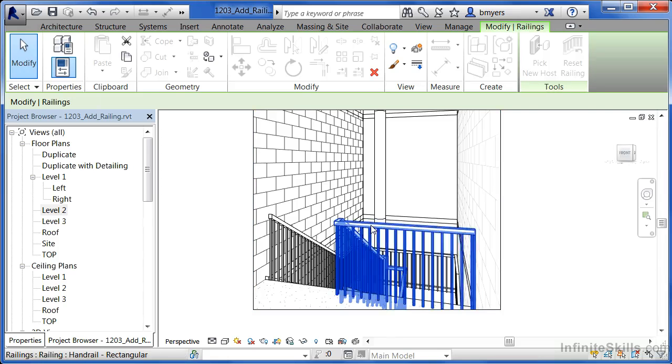So the magic behind doing railings is either executing the railing command or selecting the piece of railing, then drawing in the path that you'd like that railing to follow, and the path will automatically follow that all the way on around no matter where you draw it to.